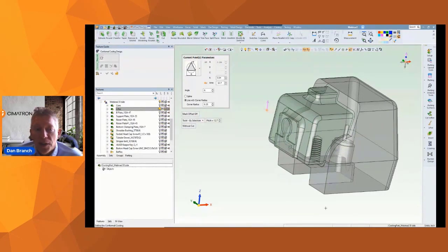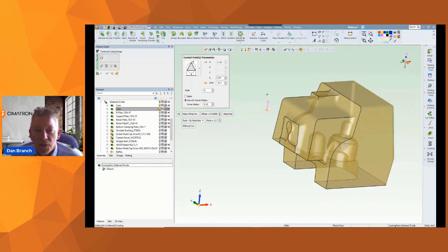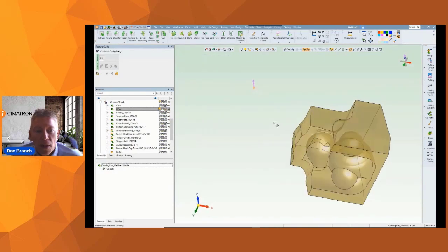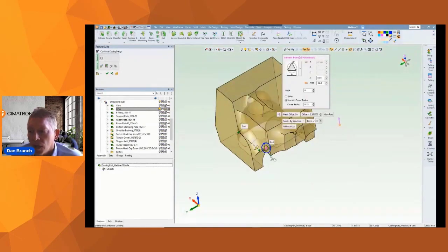Now, the system wants you to define the path, and you could spend a lot of time thinking about it, drawing a bunch of very specific curves through a part. But let me show you our cool idea to make that easier. I want the system to create a new lifter body, one that has every face offset inward from the actual steel. So theoretically, if I plot a course across this new body, the cooling channel is going to be at a constant depth from the skin of the lifter, the actual surface, to promote good heat transfer. So here I'm going to give it a little more realistic offset. We need some room, and then just start picking points that will lay out a conformal cooling pathway.